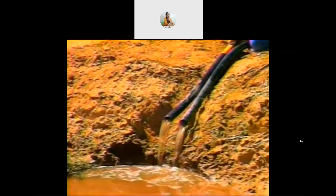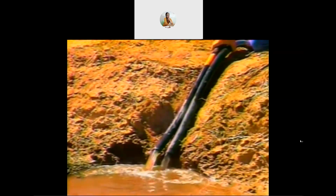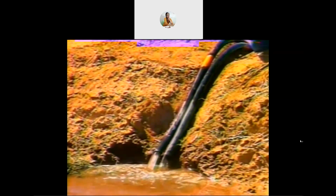The water that flows below the root zone is no longer available to the plant. This excess water is called deep percolation. Your goal is to apply just enough water to fill the root zone without deep percolation.